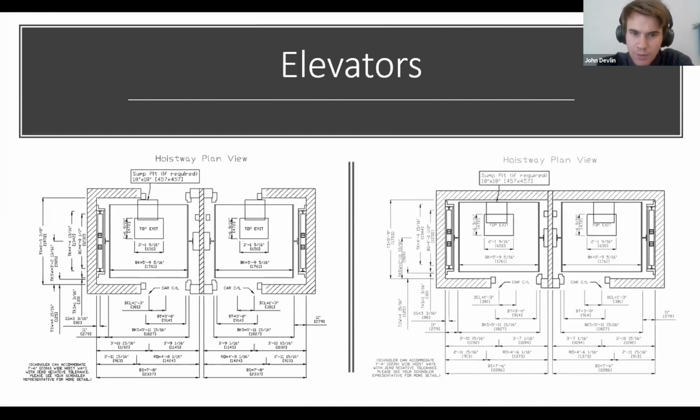The elevator will be supported by a surrounding shear wall system with I-beams at the top going across into steel plates. The loads that are to be applied to these beams were given to us by the Schindler Elevator Corporation and will be discussed later on.